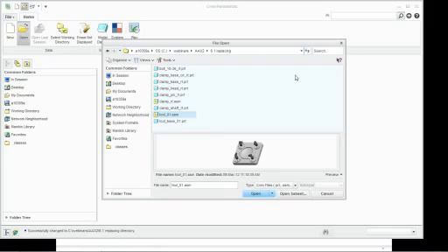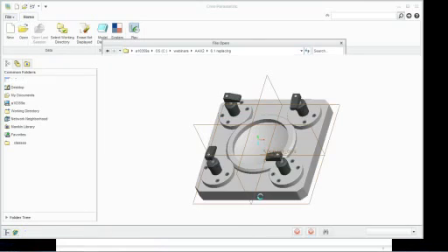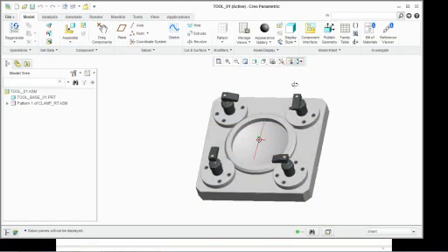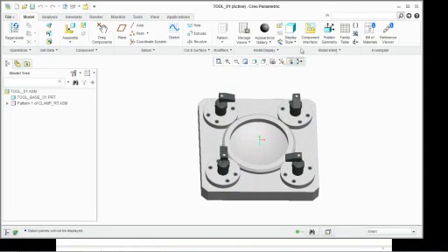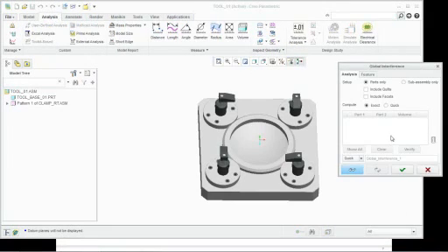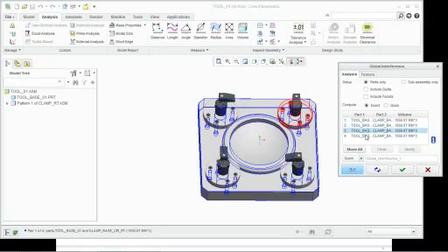So first, I'm going to show you guys how to do some component replacement. We're going to open this assembly. Let's say that this is something that we've designed. Turn off my datum features there. And right at the end, you go in and you do, let's say, an analysis, and we're going to do a global interference check. So we're going to preview this, and we notice that it's interfering in 4 places.